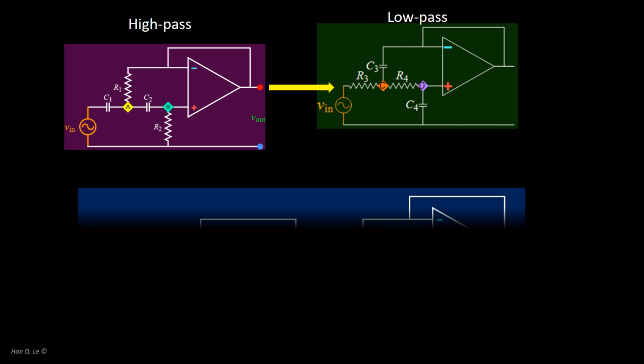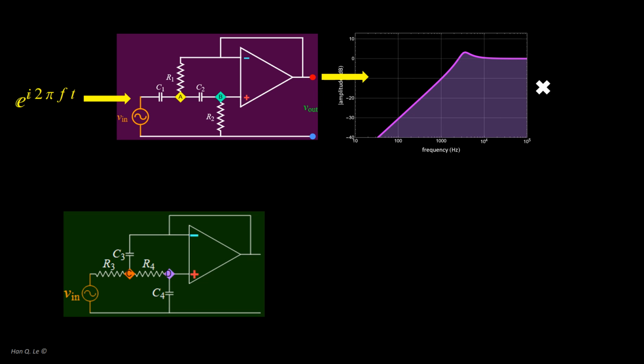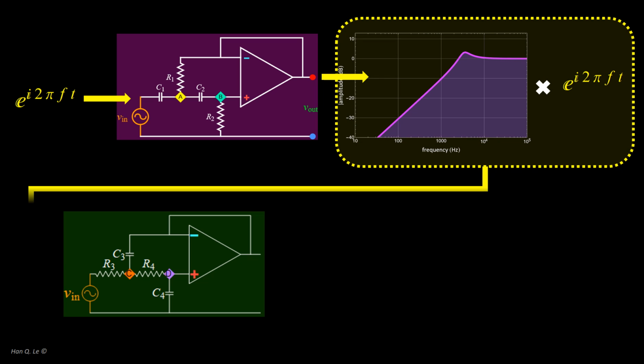The circuit of this part is the resulting connection of the high-pass circuit of part A to the low-pass circuit of part B. Obtaining the response function of the combined circuit is quite straightforward. It is the product of the two response functions.